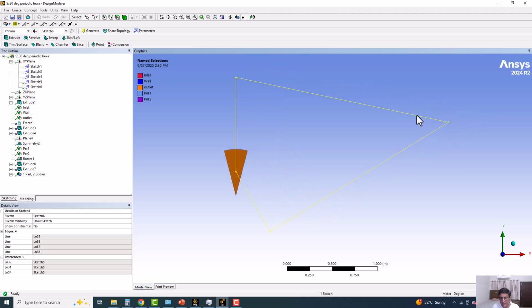And then I joined this line and this line with a straight line. So the dimension of these lines or angle of these lines is not important. It should be outside. That's important. Here this line and this line, they should be exactly on. So either you can put the angle here with the y-axis, or you can just align with the line over here, and this line is a vertical line.